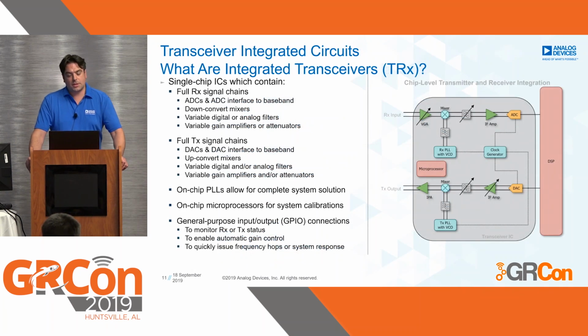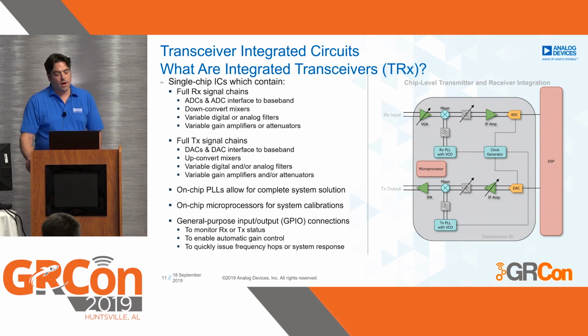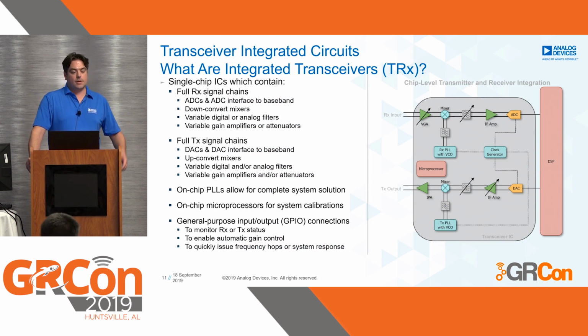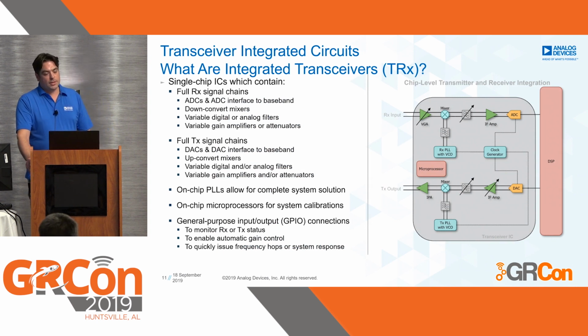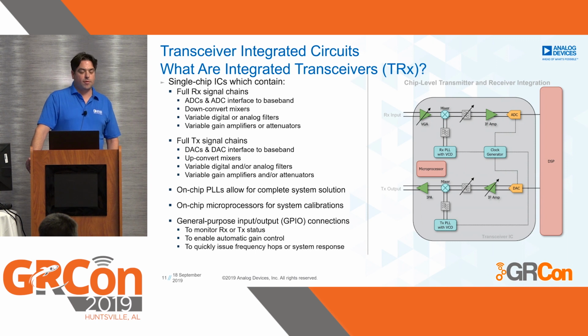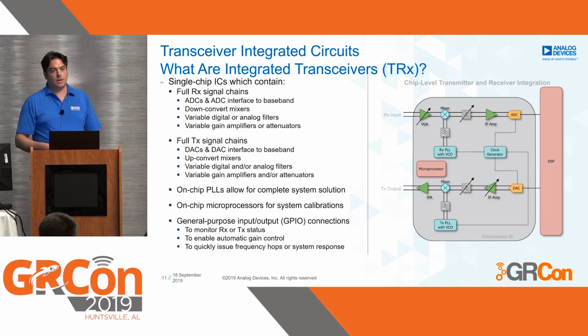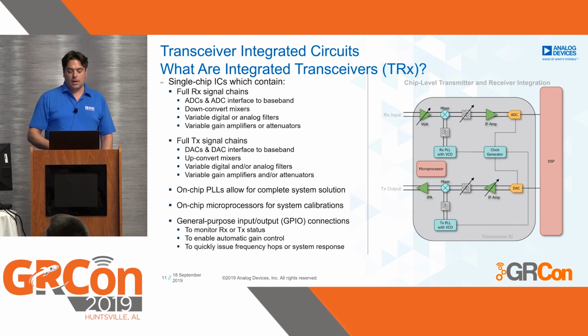I mentioned integrated transceivers. What are those? It's basically a single chip which contains a full RX and a full TX path with ADCs, DACs, down converters, mixers, filters, gain amplifiers, and so forth. There's often a microcontroller on chip which does a lot of additional calibrations.